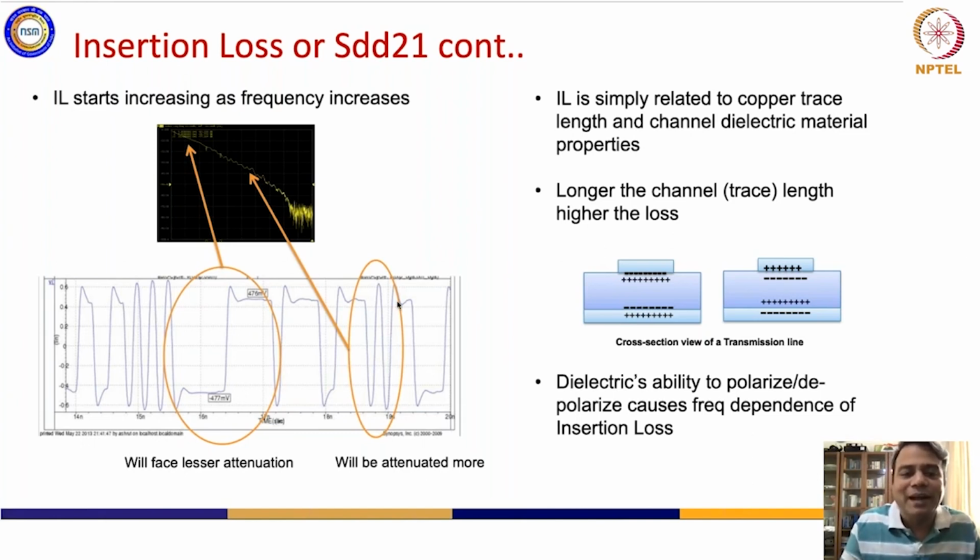So you're actually transmitting a wide range of frequencies. It's a wide band. And obviously, the attenuation of the media to the lower frequencies corresponds to the left side of the spectrum. When you go to higher frequencies, you have more attenuation. That is a standard property of copper conductors.